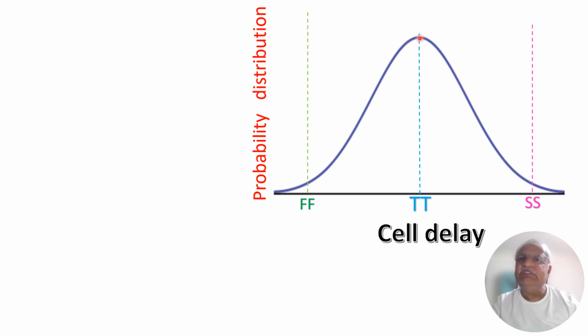So this one we consider to be due to nominal or typical NMOS, and then when it has the typical PMOS situation, we will consider that this delay has occurred, and this is their probability. That is how we denote this mean, and the first letter belongs to the NMOS, the next letter belongs to the PMOS.